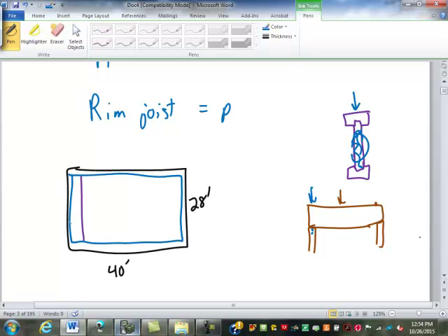So you use a rim joist around the outside where the walls of your building are going to be. That rim joist then holds up the wall so that the I-joist itself doesn't get squished. Your rim joist is usually a solid piece, like an LVL type lumber that is exactly the same height as your TGIs. I've seen people try to use 2x12s for a rim joist with TGIs.